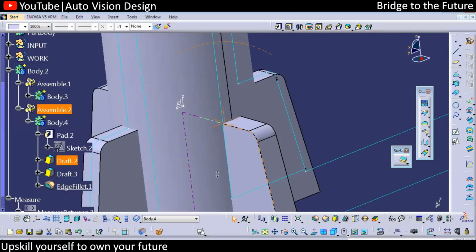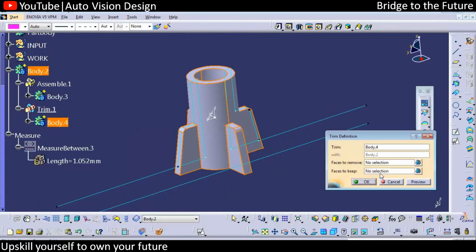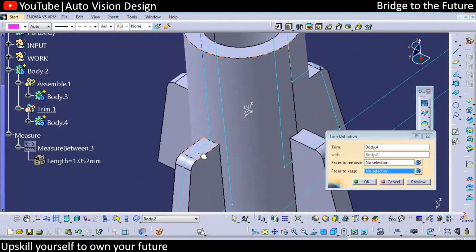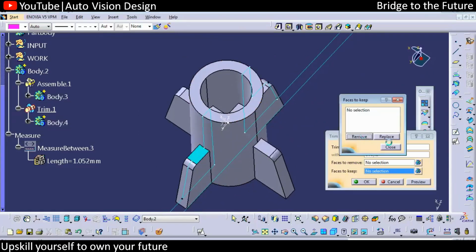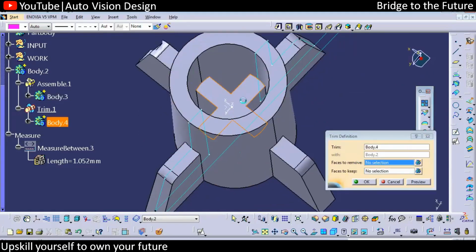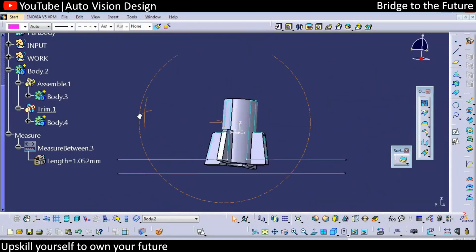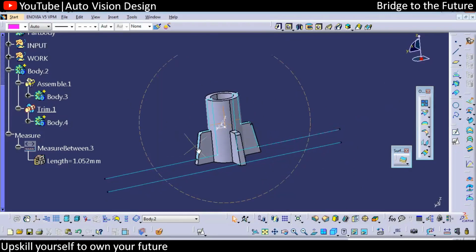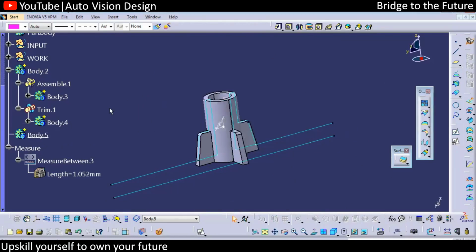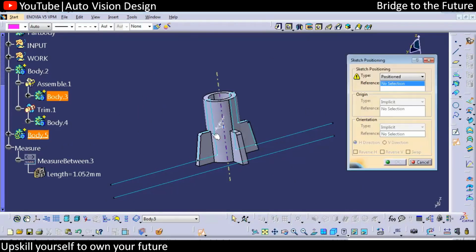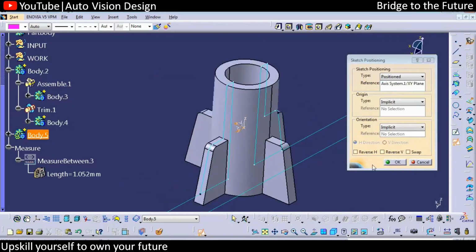Now with respect to that, we need to go for creating this assembly, so we will go for union trim. Whatever you want to keep, we can select. Here the better option will always be to select remove. Something like this, we can select remove and we will get that particular boss. For that reason we are going to check with the master section. Again, the bottom portion is not required to create, but for your clarification I will draw that too, to give you a clear idea about what exactly we have drawn with respect to the master section.